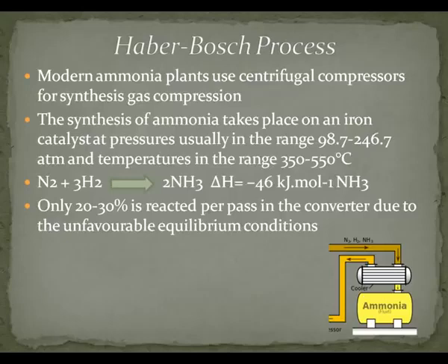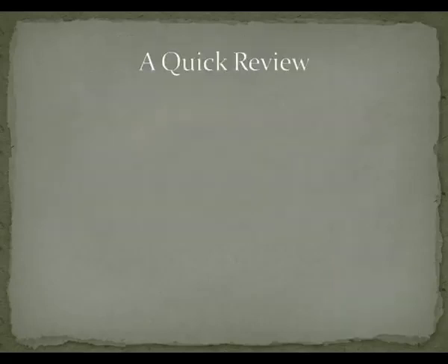However, high pressure plants are expensive to build and maintain. A German chemical engineer, Carl Bosch, solved this problem by designing a double-walled steel vessel that could operate at several hundred times atmospheric pressure. Modern plants operate at pressures in the range of 2000 kilopascals to 3000 kilopascals.